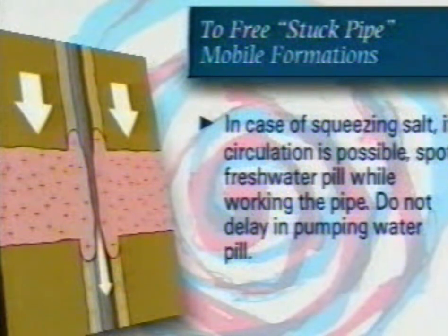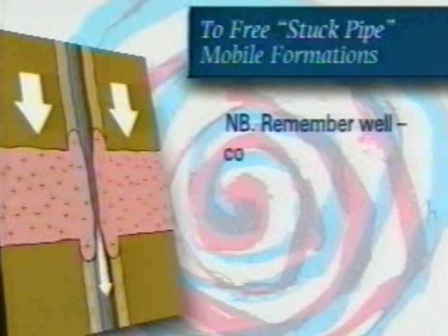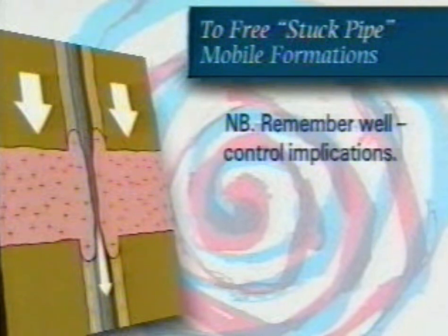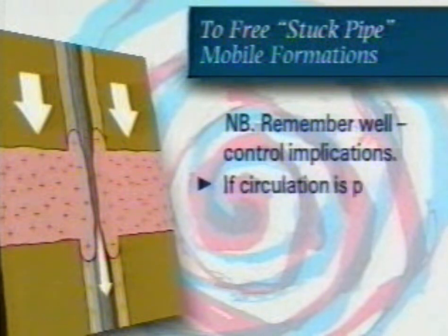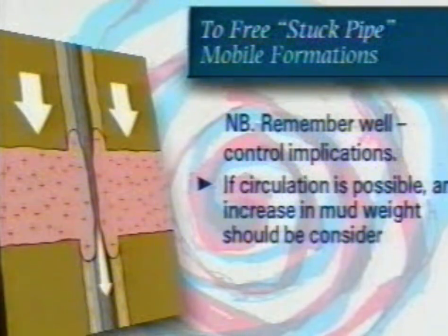And if the pipe is not free in 1 hour, repeat the procedure. Be sure to remember any well control implications. If circulation is possible, an increase in mud weight should be considered.